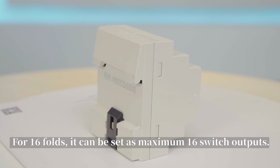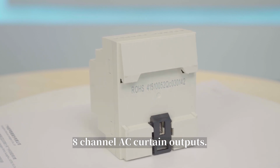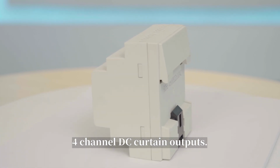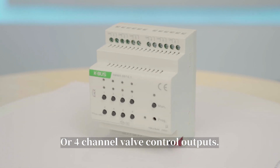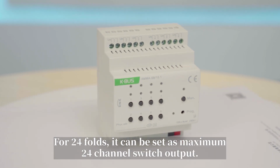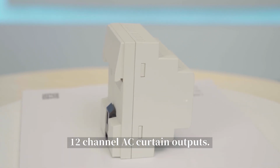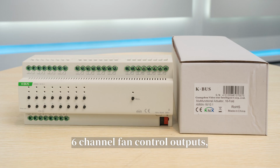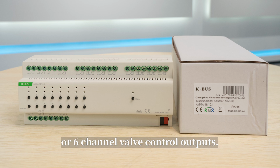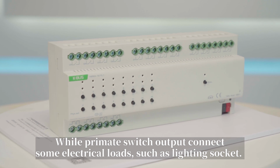For 16 volts, it can be set as maximum 16 switch outputs, 8-channel AC curtain outputs, 4-channel DC curtain outputs, 4-channel fan control outputs, or 4-channel valve control outputs. For 24 volts, it can be set as maximum 24-channel switch outputs, 12-channel AC curtain outputs, 6-channel DC curtain outputs, 6-channel fan control outputs, or 6-channel valve control outputs. The output requirements are configured via parameter.